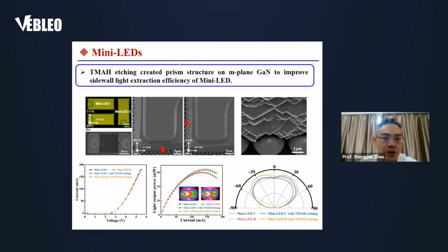With low temperature gallium nitride, aluminum gallium nitride nucleation layer, gallium nitride grows on the C-plane sapphire region and cone region. With sputtered aluminum nitride nucleation layer, gallium nitride only grows on flat C-plane sapphire region.